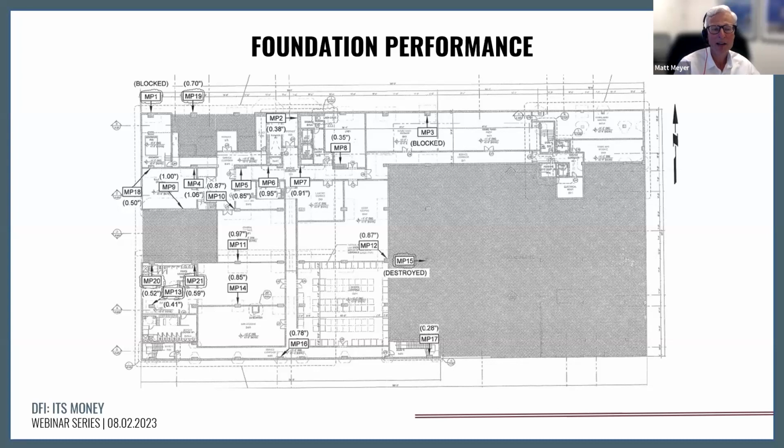We would get a plot of basically settlement at each column or shear wall with the number of elevated levels, so we could react if we had to adverse performance. But fortunately, there was no adverse performance. As you can see from this information, the settlement is very compatible throughout the areas of the medium length, variable length foundation system and the long piles.